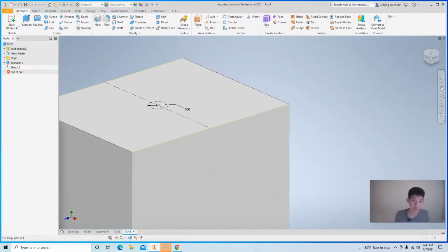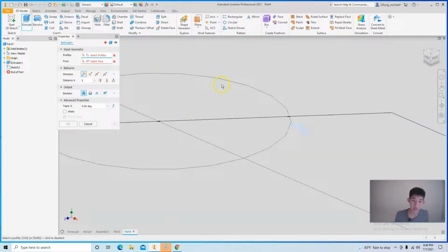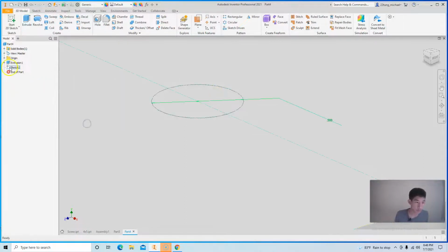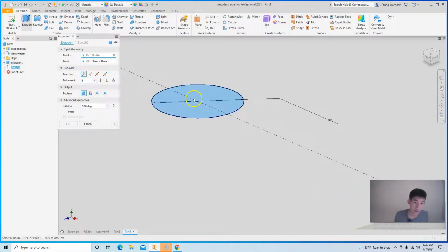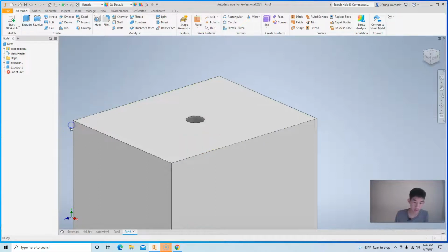We're going to finish the sketch, and then we're going to extrude, and nothing happens because this is a construction line, and the computer is like, we're not touching this. So we're going to want to make sure that we use our actual full circle and that it's not a dotted line. And finish, and now we can extrude. But we want it extruding the other way, and we want it to only go 1 inch. So we'll make that, click OK.